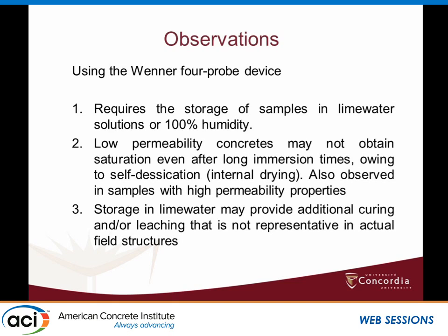Also, when you store in lime water, maybe the samples are going to have an additional curing and leaching and all the things that my previous colleague explained. So this is not how the real structure in the field is going to behave.